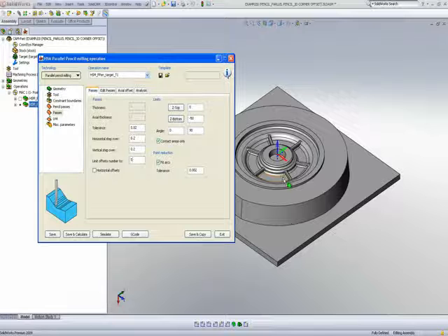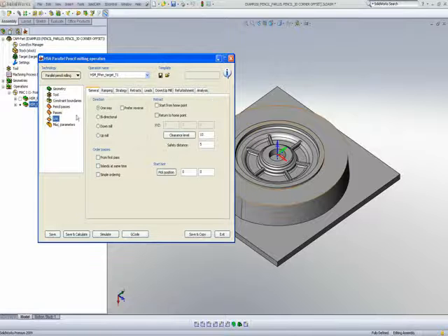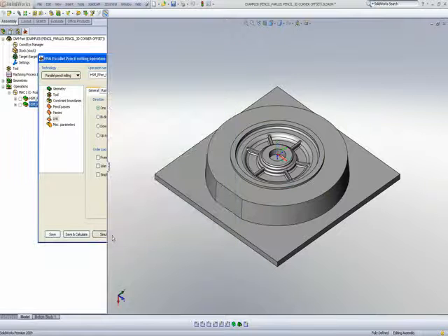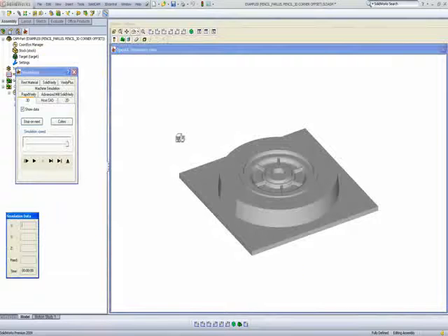In other words, it'll start from 1 millimeter outside of the part on both sides of that particular step. Let's take a look at our link area first, and we'll keep it at one way, or we can do bidirectional, and I'll leave it right now at one way. And now we'll just do simple save and calculate, and then we'll simulate our part.